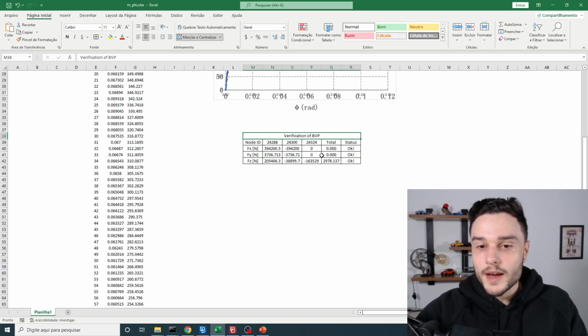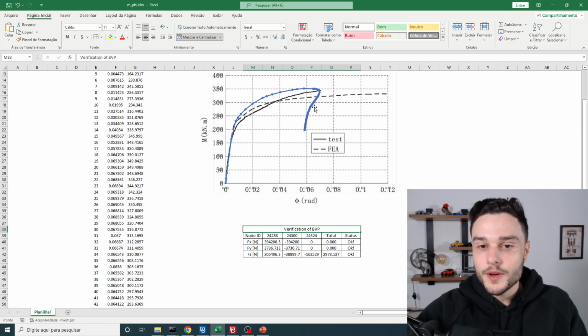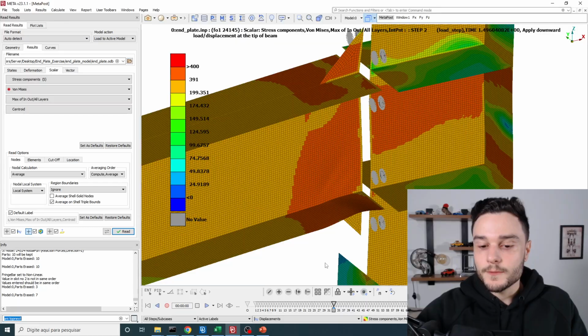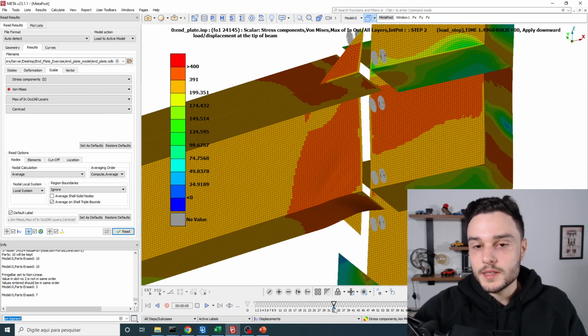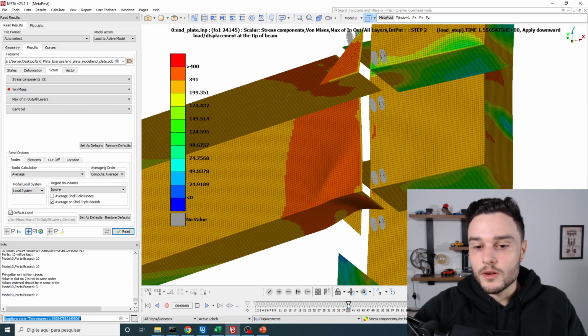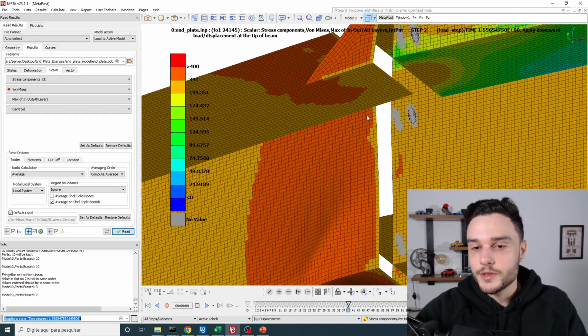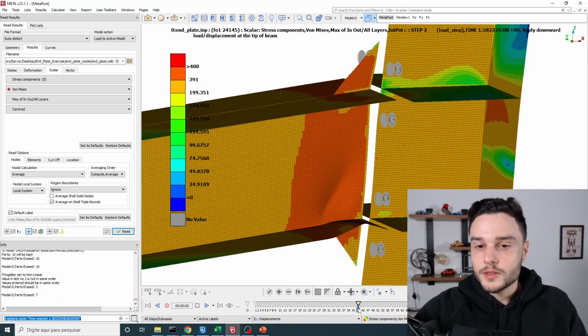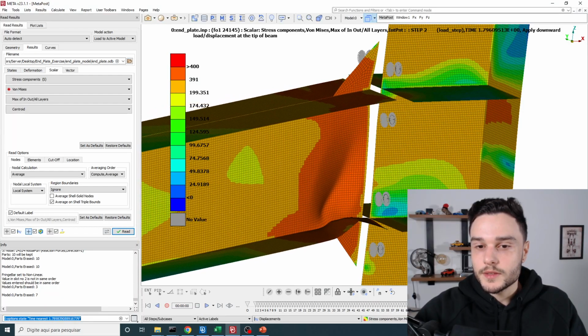And that's why we have this inflection point here. We have this loss of stiffness for the structure as a whole. Here we have the collapse of the structure, which is when we have this whole section with plastic strain, with plasticity occurring, and this whole section lost most of its stiffness. We do have some region here yet, but it lost most of its stiffness.